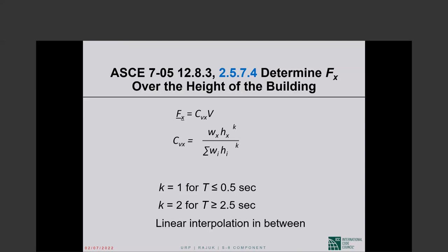If you take that option, you are dumping more of the lateral load towards the top of the structure, thereby getting larger overturning moment for the same base shear, which is essentially penalizing your client for no reason at all.